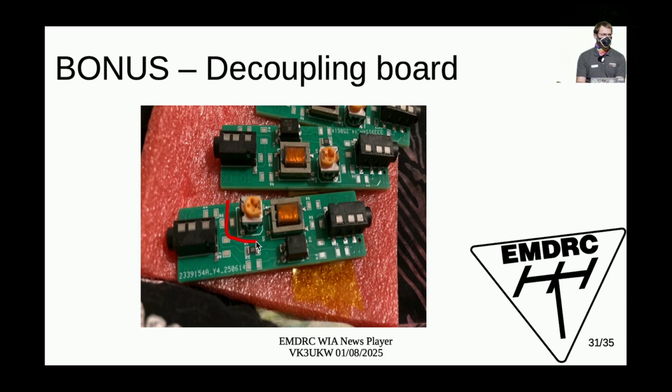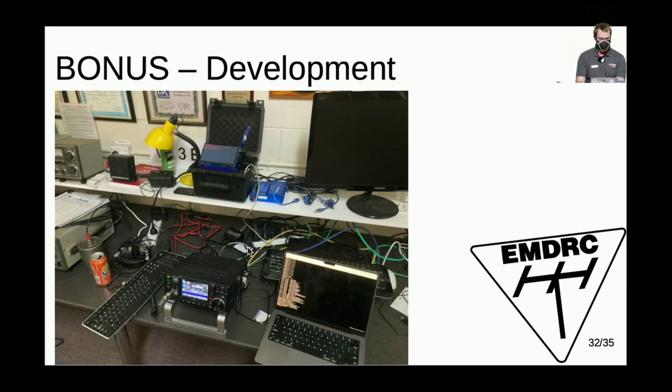What we could do was put in a pretty high level on the computer side to get over the noise floor that we have on the sound card or on the computer side, and then attenuate it in this board down to the level that the radio wants.